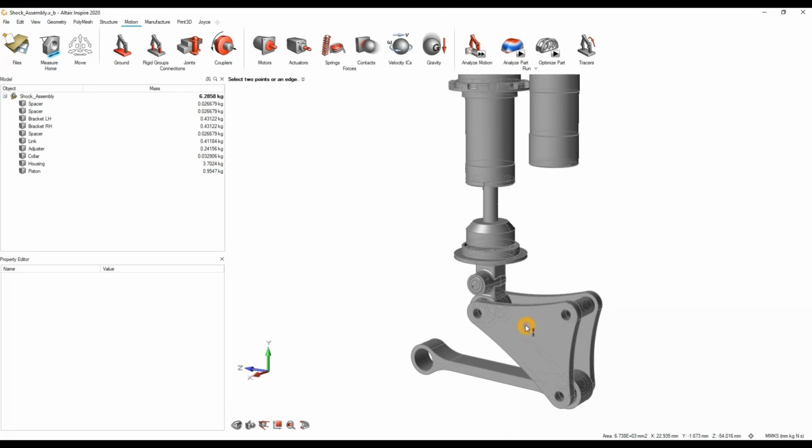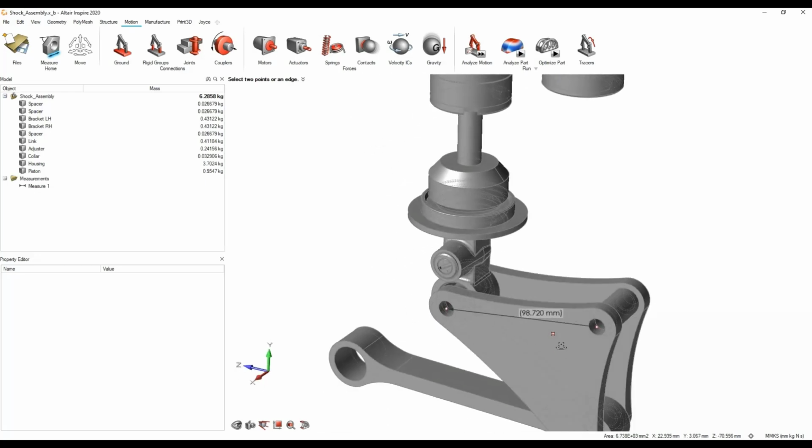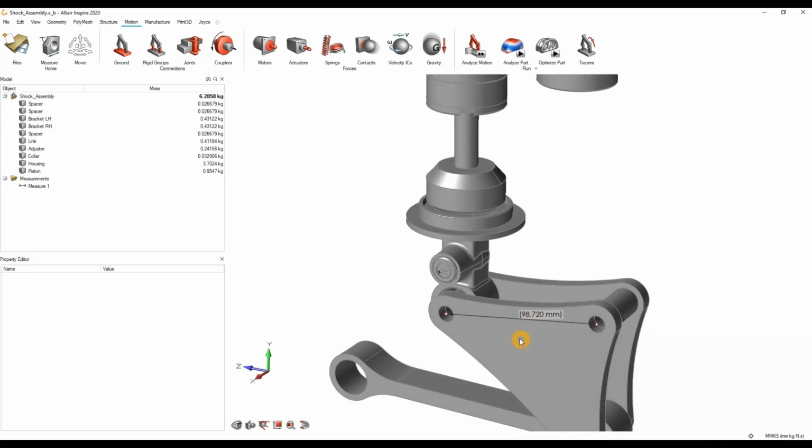Now you'll see within Inspire, you also have what we call the snap detection tool. It's very intelligent with its geometry feature recognition tool, in that if we want to measure the midpoint of a line, it tells you where it is, so you don't need to go through and calculate the full distance and then try halving it. Just by hovering over certain elements, you can find the center points of different parts, and you can see very quickly just how big that part is. And obviously if you don't want to see it anymore, you can just delete it off.